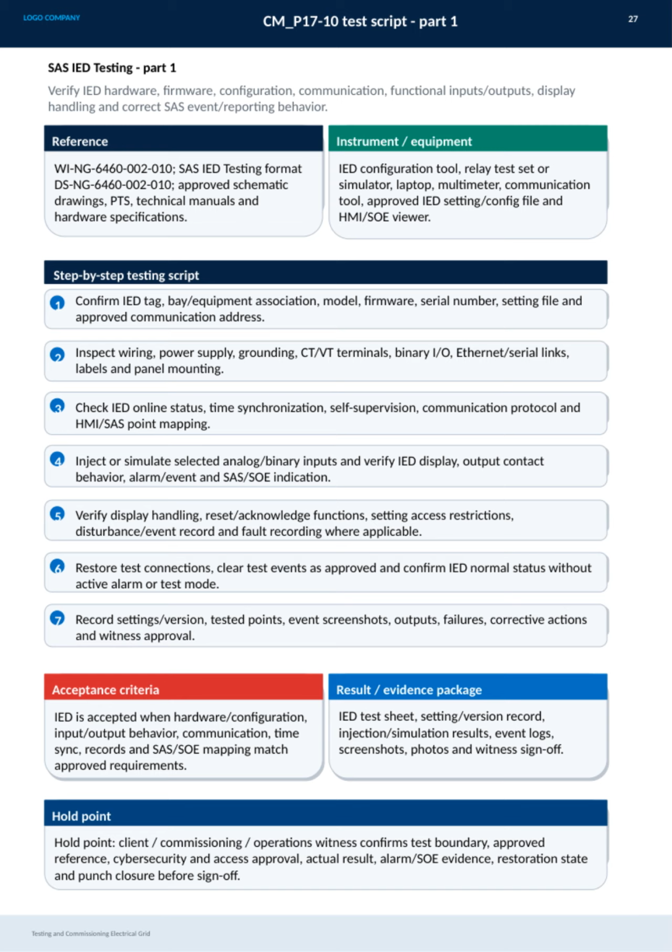Throughout the process, detailed records of settings, versions, tested points, outputs, failures, corrective actions, and witness approvals are logged meticulously. The IED is accepted only when hardware, configuration, communication, and all functional behaviors conform strictly to approved requirements. Finally, the result package includes comprehensive test sheets, logs, screenshots, and a signed witness record to ensure accountability and traceability. The hold point ensures client, commissioning, and operations personnel confirm all aspects before final sign-off, including cybersecurity and access approvals. This approach guarantees that every detail is correctly validated before the IED is commissioned for operation.